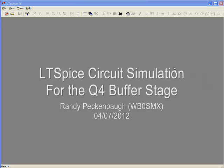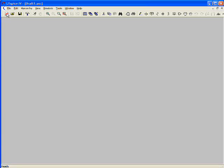So within the overall LTSpice window, you've got all your tools up here, and the first thing we want to do is start a new circuit by clicking on that little white LT up there. That starts a new circuit, and then we can simply start placing components. This is a fairly simple common emitter amplifier.